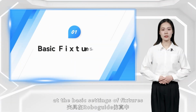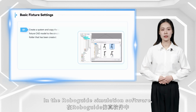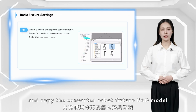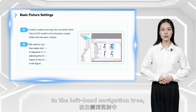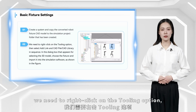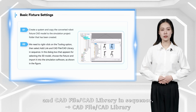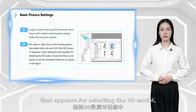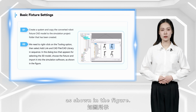First, let's take a look at the basic settings of fixtures in the RoboGuide simulation. In the RoboGuide simulation software, we first need to create a system for the robot and copy the converted robot fixture CAD model to the simulation project folder that has been created. In the left-hand navigation tree, we need to right-click on the tooling option, then select Add Link and CAD File, CAD Library and Sequence. In the dialog box that appears for selecting the 3D model, choose the fixture and import it into the simulation software, as shown in the figure.